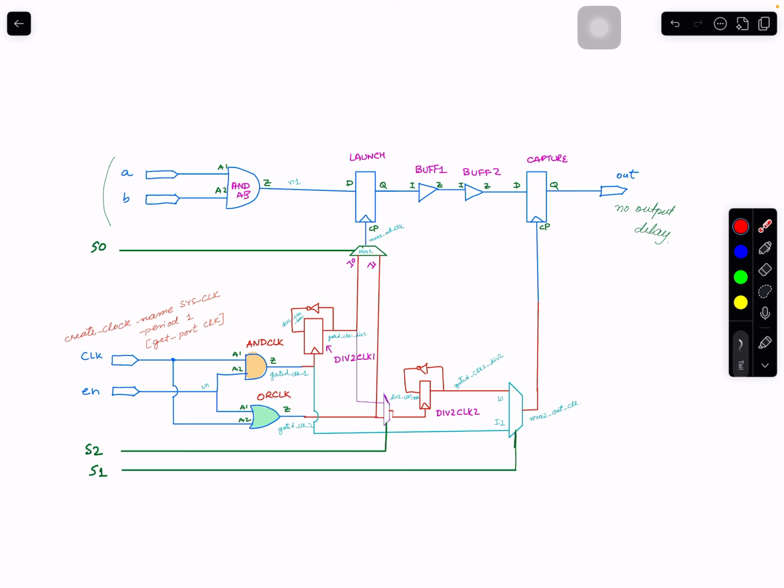Now it could be that you have a clock coming here and there, they have a timing path but those are not valid because based on what you select on your chip, they might not come together. In that case, you need to define false paths or MCPs, whatever, if there are violations, right? So if you don't create a mode, then you need to get ready for a lot of MCPs or false paths for setup and hold. And we talked about those, remember?